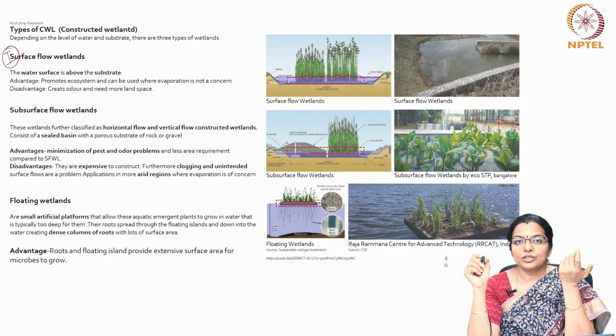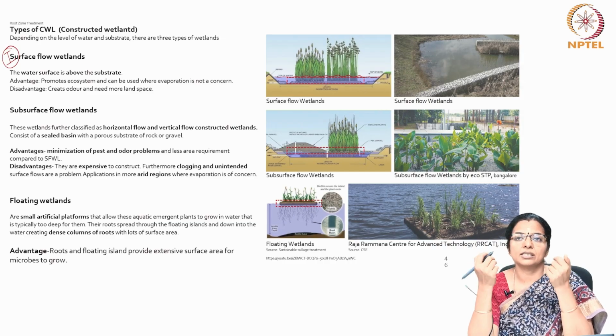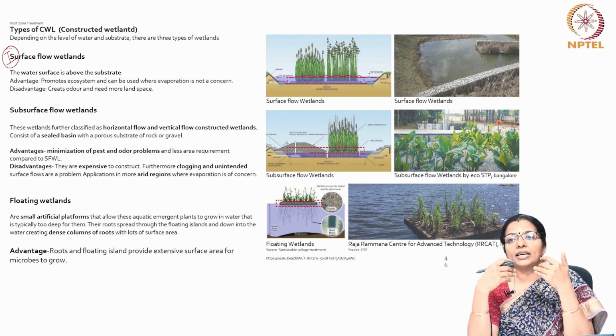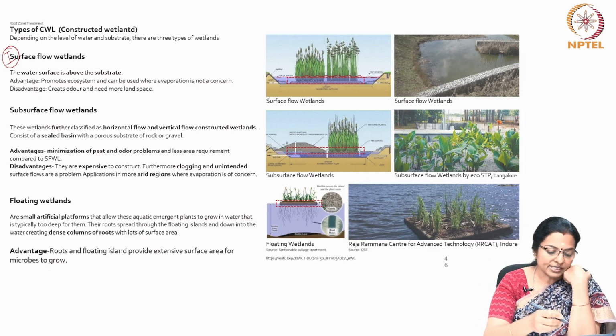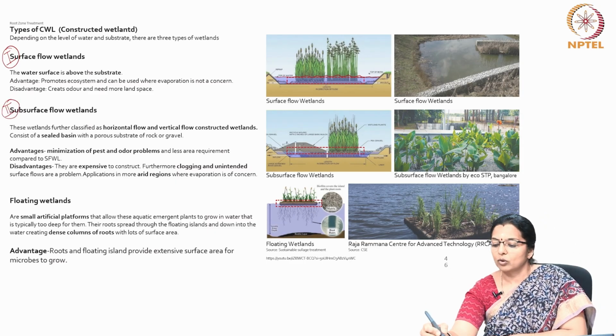The advantage of this system is that it promotes ecosystem and can be used where evaporation is not a major concern. The disadvantage is that it creates odor and needs more land space. The second is a subsurface flow wetland, which is this.